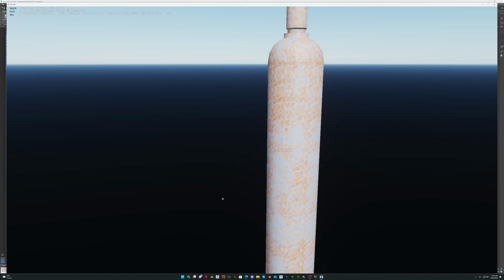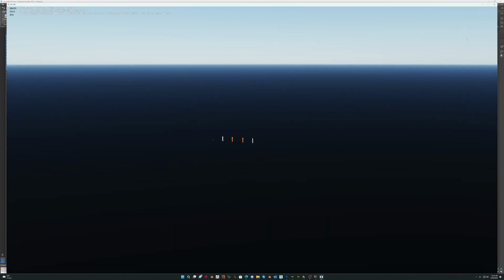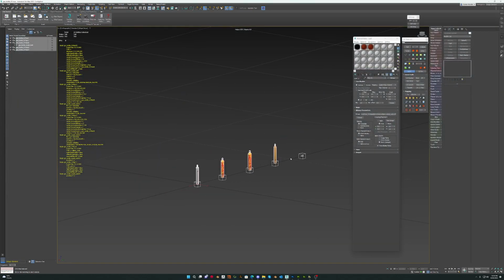So if I put this outside a house and I wanted that to be specifically blue, and I was using a palette where one of the colors was blue, I would have no control of which color that would choose. So what I would do in that instance is I would request, if there was no blue available on a specific line, a line to be added to the fabric palette, and provide myself or Norfolk the RGB values of that palette. Okay, so now we've palletized our model.